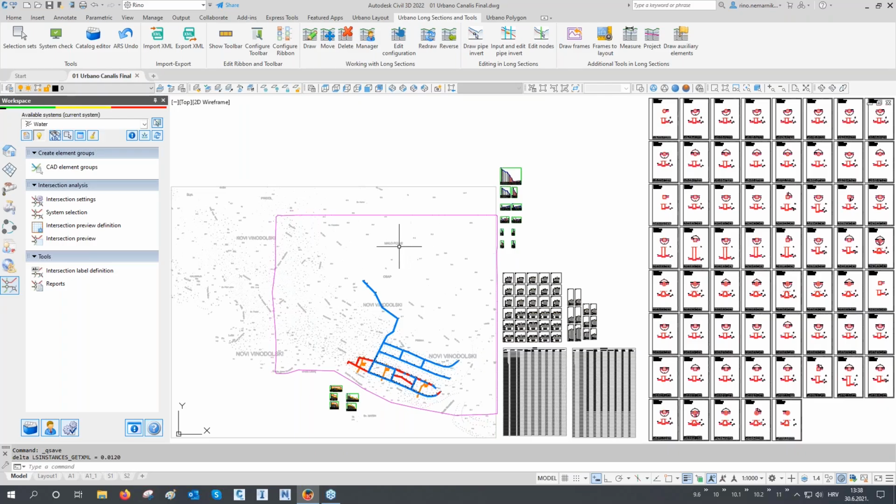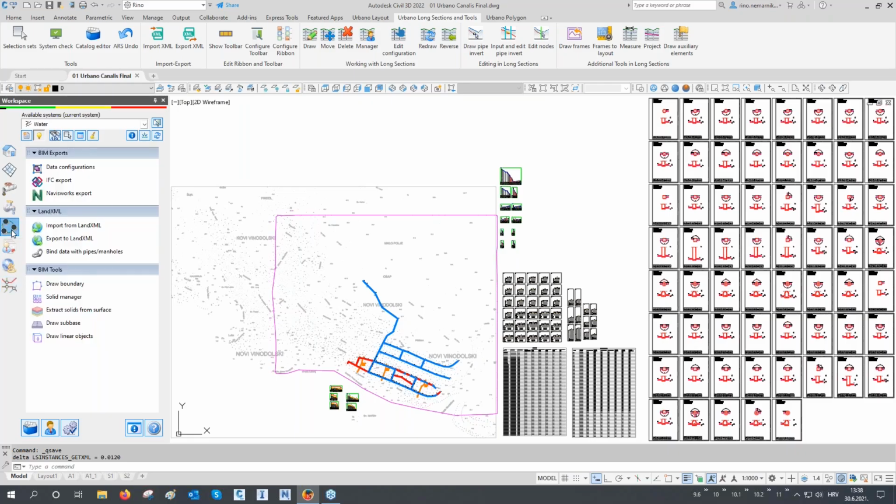To export, you have to go to this BIM panel, where we have functions for IFC export, Navisworks export, LandXML import and export, with which you can communicate, for example, with Autodesk InfraWorks and Autodesk Civil 3D. With IFC, you can basically go to any software like Revit, for example. And of course, with the Navisworks NWC file, you can directly go to Navisworks. With IFC, you can also go to Navisworks, and also to other IFC and BIM software not from Autodesk.